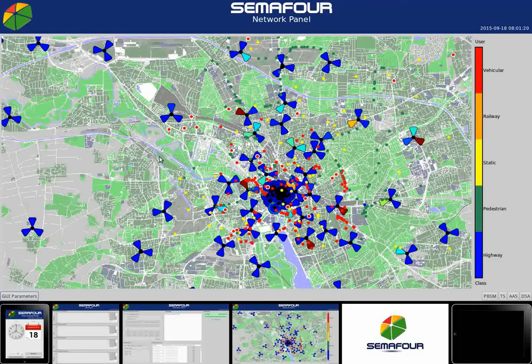In the demonstration scenario, the frequency resources of the macro cell are reused in both the inner and the outer cell, while the original macro cell's transmit power is split between the two cells. When deployed effectively, vertical sectorization enhances network capacity and hence service performance. As we did previously, we first consider a baseline scenario where the SON function is switched off.